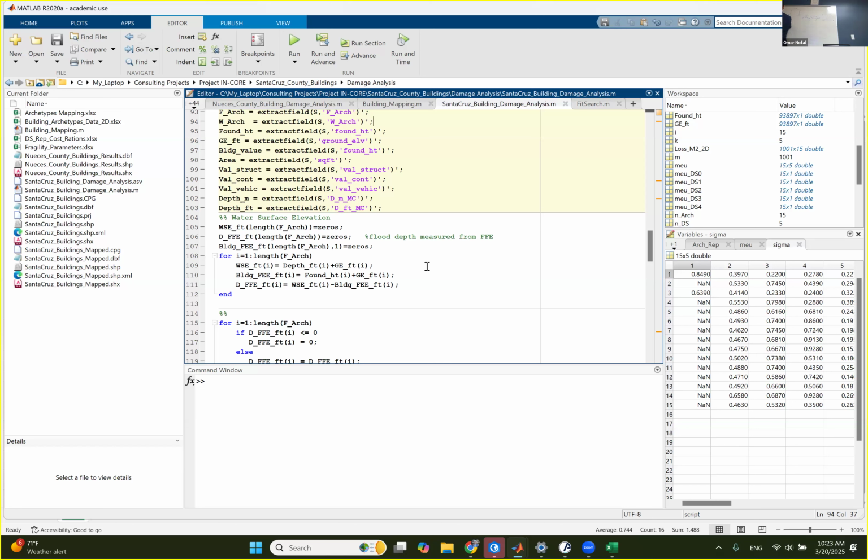Then you have the flood depth measured here, h equal to 6 feet. So basically you can get the water surface elevation. By the way, this is depth, but this is elevation, measured to the mean sea level. So the water surface elevation is going to be 126 feet. You guys got that? But this is the water surface elevation, the water height measured from the ground elevation that we got from the map.